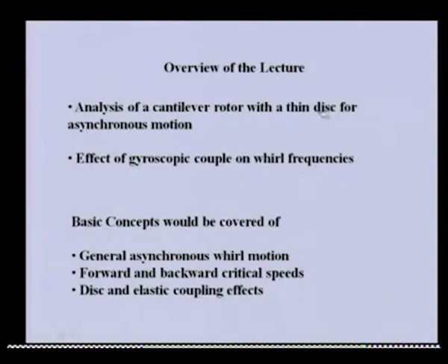In this case, we will be considering both translatory and wobbling motion of the disc. The effect of gyroscopic couple on the whirl frequency will be analyzed. Some of the concepts we will be covering in this lecture are general asynchronous whirl motion, forward and backward critical speeds, and disc and elastic coupling effects on the whirl frequency. These are the analyses we will be doing.